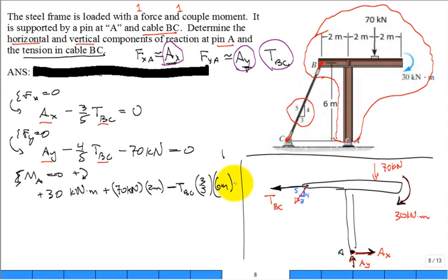And then I need to continue this equation, so it'll be the tension B to C, and now our downward component, I know I'm exaggerating their lengths, and first of all I have to pick off the component, isn't it 4/5 downward? Okay. And then what is its moment arm distance? 2 meters. And does it make it want to rotate in a positive, negative sense, right? Negative. So they have to sum to 0. We pause. We triple check our work.